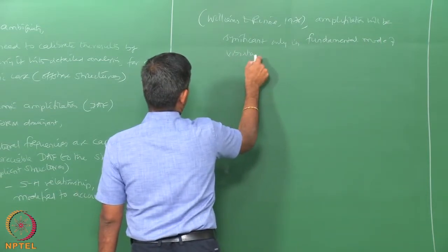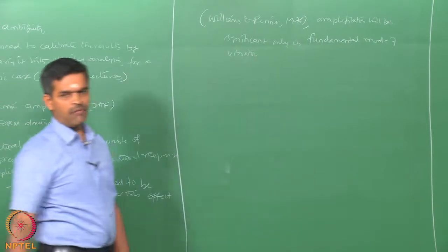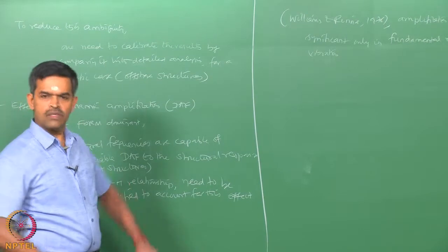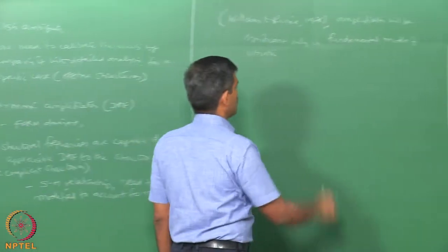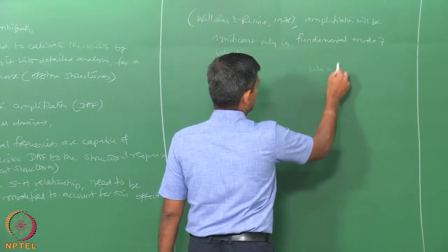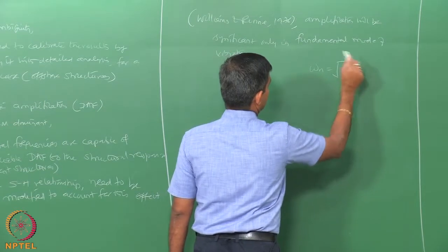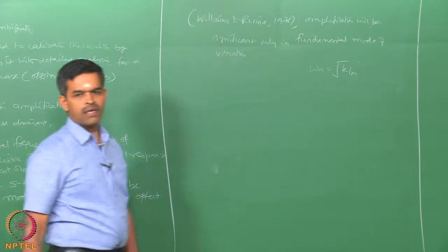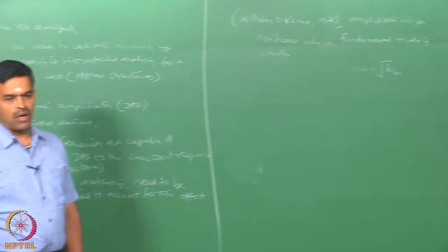So, as a designer, one needs to be careful in fixing the fundamental mode of the system, because we all know that the fundamental mode of vibration is a structural characteristic where mass and stiffness of the system can be adjusted accordingly.